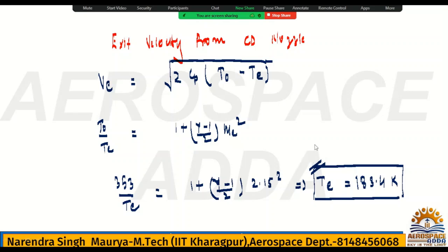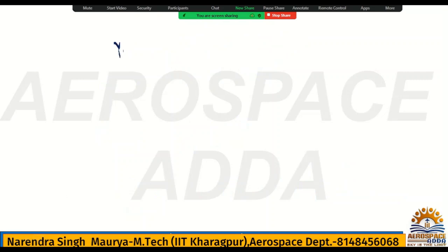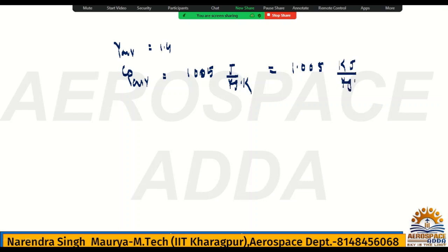Now check. So T naught we have, and Cp for air, since you have taken gamma as 1.4. At that time I told you Cp is 1005 joule per kg Kelvin, or also 1.005 kilojoule per kg Kelvin.